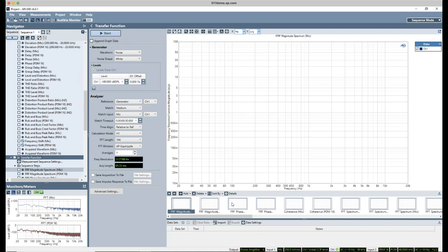There's all kinds of good reasons for doing that. The downside of doing that, particularly when we're measuring microphones that are going to be used in a voice application, is that very often the device may be doing some active signal processing and will have a non-linear response to a sine wave. In fact, to put it in short, many voice processing systems try to cancel sine waves. It's not human speech. It's not a desirable signal.